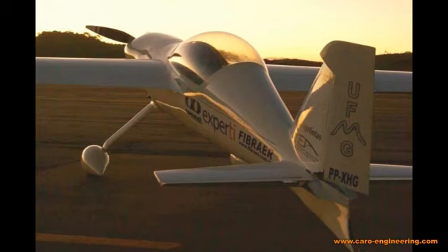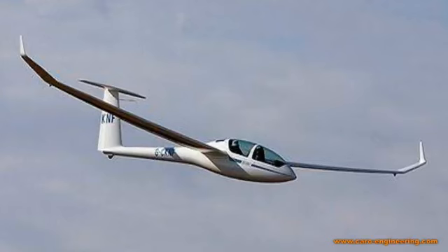On the fuselage, design for laminar flow is also important but more difficult to achieve because of things like cowlings, doors, windows and other things that would prematurely transition the flow to turbulent. Surface waviness and roughness will also cause the boundary layer to transition to turbulent sooner than a smooth surface, with a corresponding drag increase, which is why the highest performance aircraft use composite materials, which allow much better surface quality than metal surfaces. You can see the result of this when you look at the highly optimized competition gliders. Composite is the only material used there.